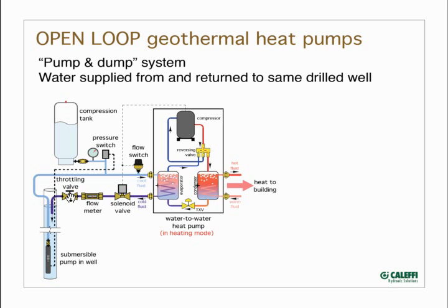If we can operate that heat pump safely at perhaps 2 gallons per minute per ton, we're going to adjust this throttling valve and watch our flow meter and keep that flow as low as we can and still get acceptable performance. Now, there are 2 things that I like to say with these open loop systems. The 2 keywords: water quality and water quantity.